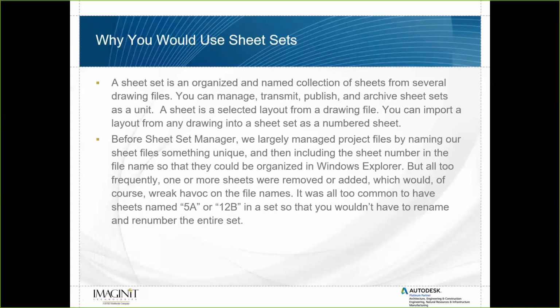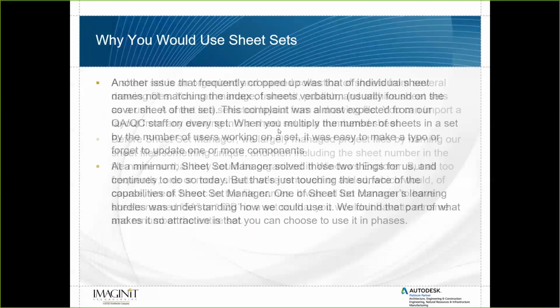The other thing is, if you wanted to print an entire project, before the sheet set manager you had to open up each drawing, plot each layout sheet to PDF, to your plotter, whatever, and then close the drawing and open up the next drawing, because most of us do not work in a single drawing. We have multiple drawings. And so that's why you really want to use a sheet set for that.